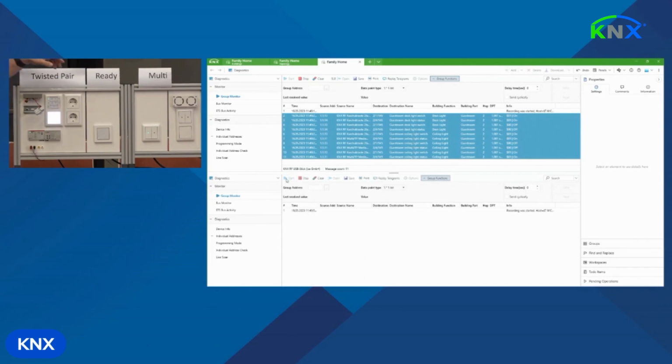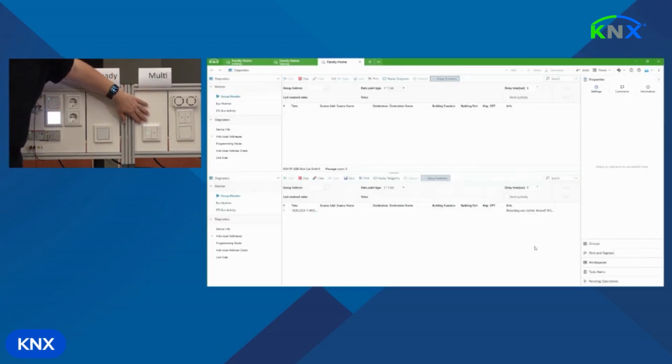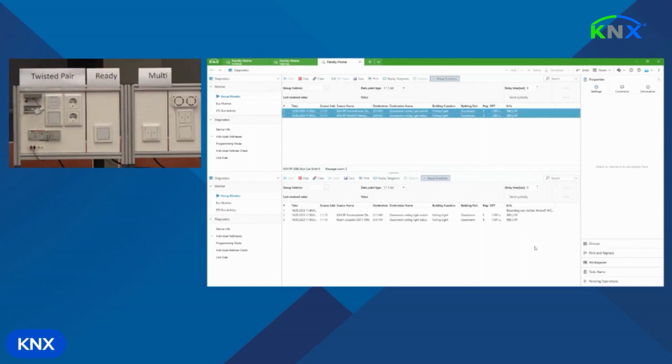We will see now, maybe clear the telegrams in the upper window. So we can see now that if I switch this off, the frame is encrypted on radio frequency, it's blue. But when it's traveling over the coupler on the twisted pair, it's unencrypted on the way from the coupler to the twisted pair actuator. Great to see it this way now, with the RF interface being secured up here and unsecured or plain down there on the twisted pair line. Yes, there's also the possibility to see this upfront in ETS.